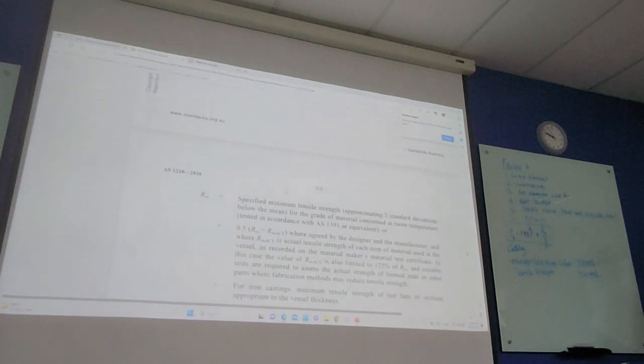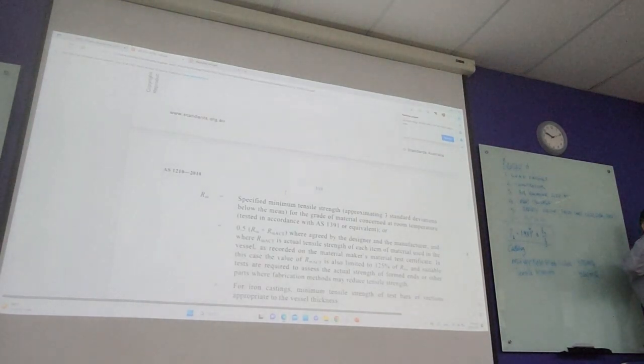Sorry, what are we doing? Oh, because we want to find out the material for the catalog, the sheet metal that we want to build the receiver with. The yield stress, yield means deform. The stress you apply until the moment the steel deforms is the yield stress. And this is your tensile strength: when you pull, you have to pull at 460 megapascal to be able to pull it apart. The yield stress means the stress at which it starts to deform and cannot go back to its original form.